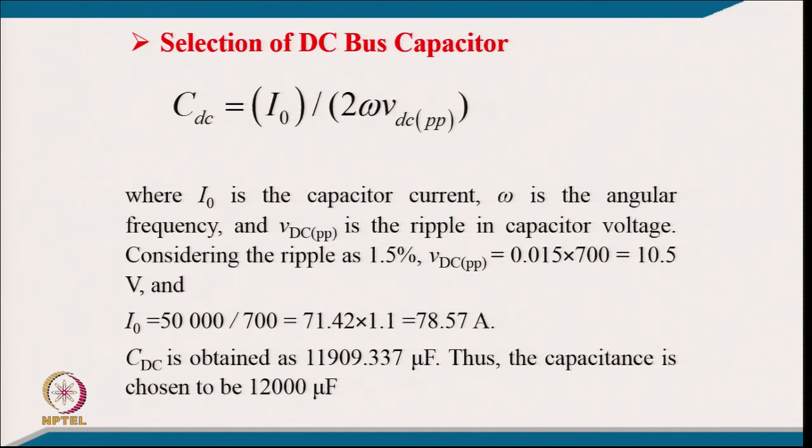The reason here is that the second harmonics typically get reflected on the DC link, and because of the presence of second harmonics on the DC link, we have to have twice the frequency, similar to a single phase inverter circuit. That is the relation it goes.